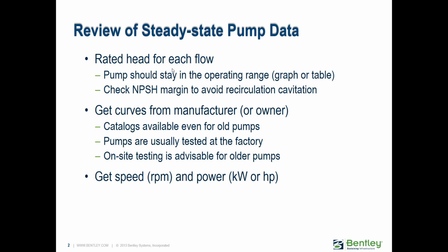When you're dealing with transients, you'll also want to check your net positive suction head, NPSH, to avoid cavitation problems. So that's a general note on pumps and what you want to watch out for.